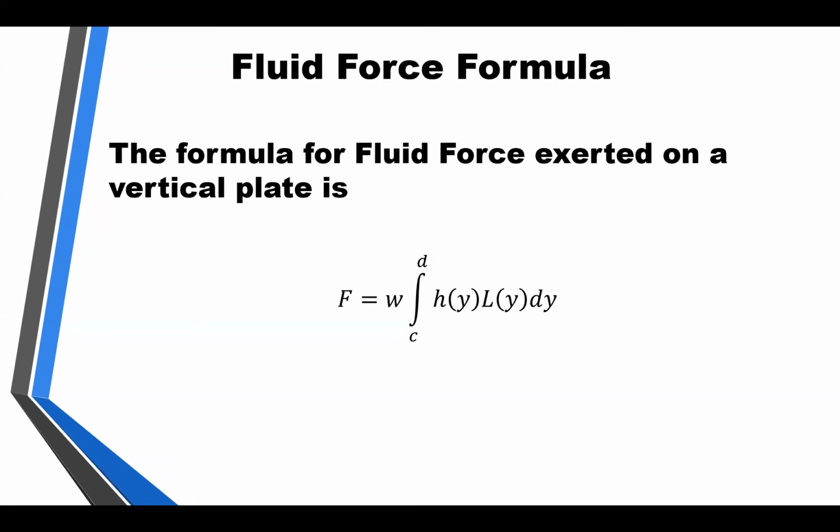The formula for the fluid force exerted on a vertical plate is weight density times the integral from c to d of h(y) times L(y) dy. h(y) is going to be the depth, how far each one of those horizontal slivers is under the water or whatever liquid we're using, times L(y).